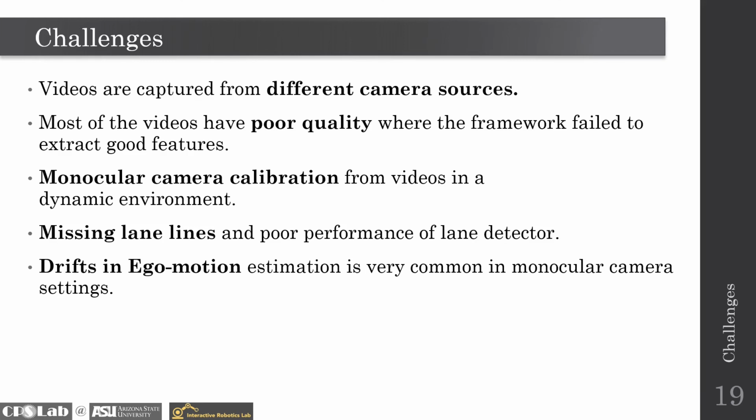Also, the missing lane lines in most of the videos make it difficult to do proper lane detection, and hence the accuracy of the ego motion is reduced. Also, drift in the ego motion estimation is a pretty common problem in monocular camera settings.